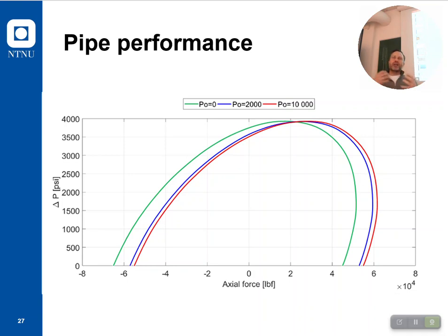Many of those calculations are based upon pure outer pressure and nothing on the inside. Also with the API formulas for collapse, there can be no internal pressure. It becomes inaccurate because the surface area also is different on the inside and the outside of the pipe.